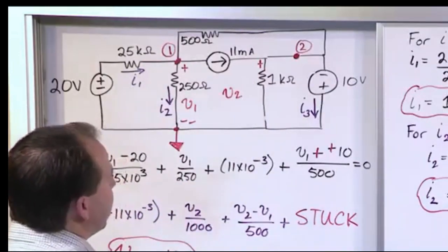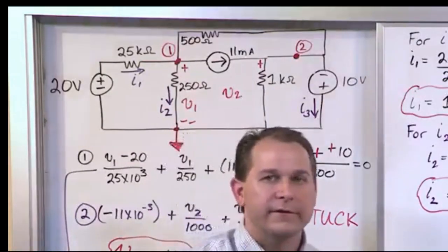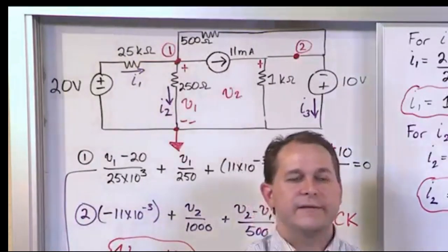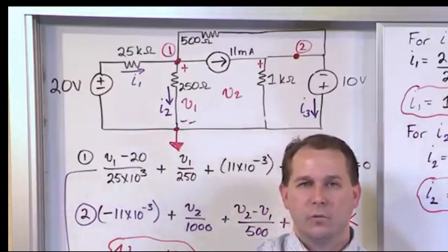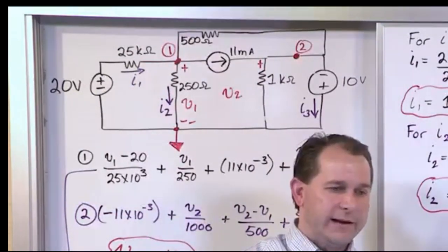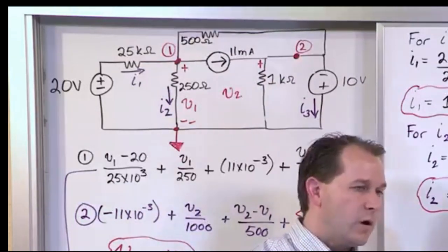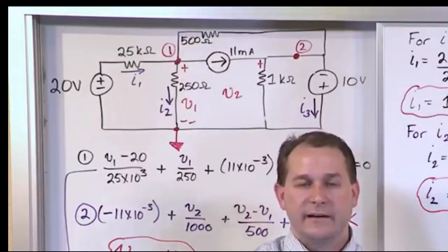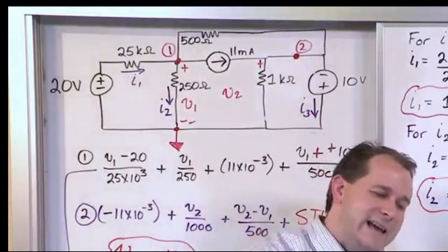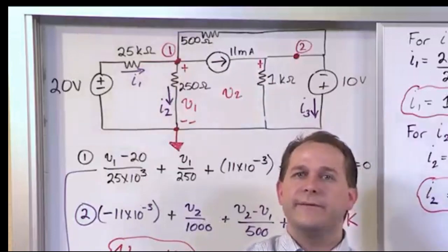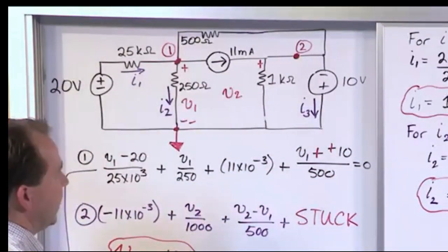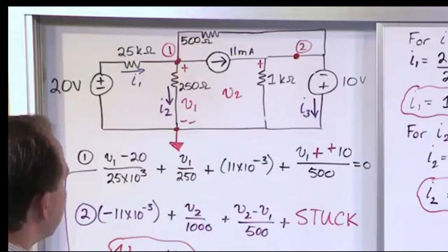We know Kirchhoff's laws are always true. That means at a node, the current going into the node has got to equal the current leaving the node. It's like water in a hose. Water goes in, water goes out. Even if you split it with a Y splitter, water goes in, water goes out. The algebraic sum has to be 0, which is the same way of saying the current coming in has to equal the current that leaves, even if it branches out. This is conservation of charge.